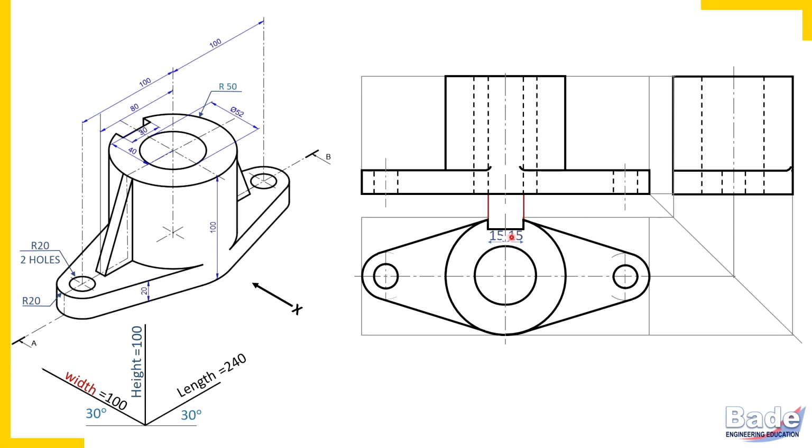Now let's draw this slot in the side view. Check all the details now. Have you realized the boundary generator of the cylinder? Check here, this generator. Correct? It is no more here because this portion we have removed. So from the left side, the generator which was initially appearing at the boundary, because of the slot, that boundary generator is no more there. So this generator, this boundary, now we will have to erase.